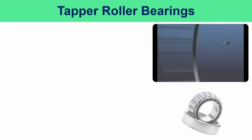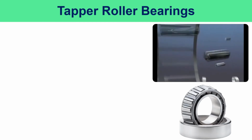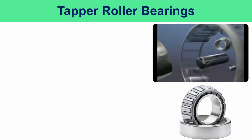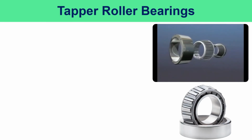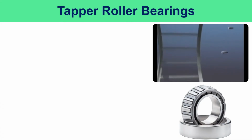Tapered roller bearings. A tapered roller bearing consists of 2 separate parts, an inner ring with a set of tapered rollers secured by a steel cage called the cone assembly, and an outer ring called the cup. Cup and cone are mounted separately. Cup in the housing and cone on the shaft. Only when they are assembled together do they form a complete bearing.